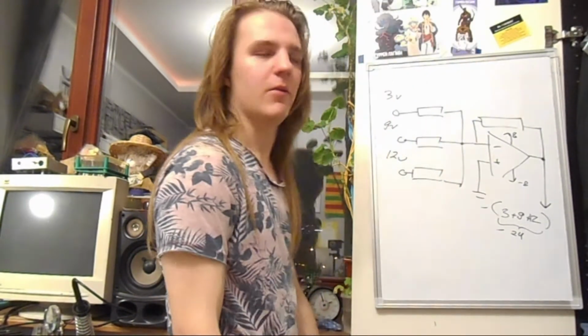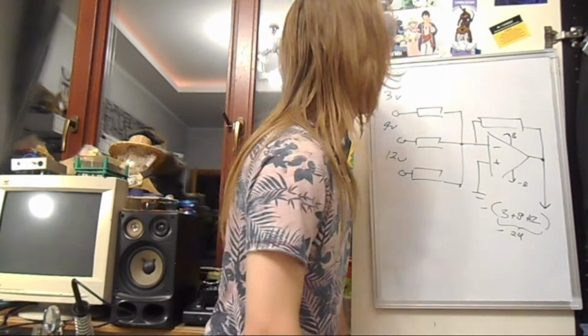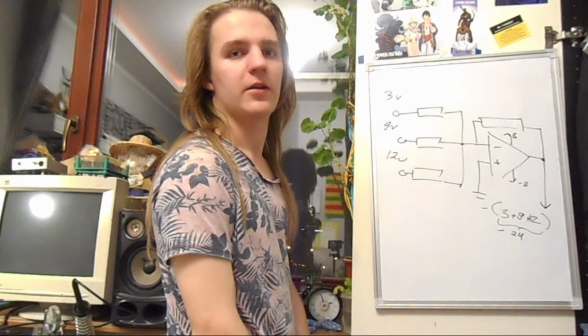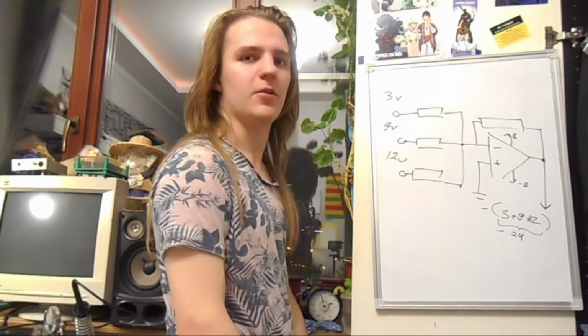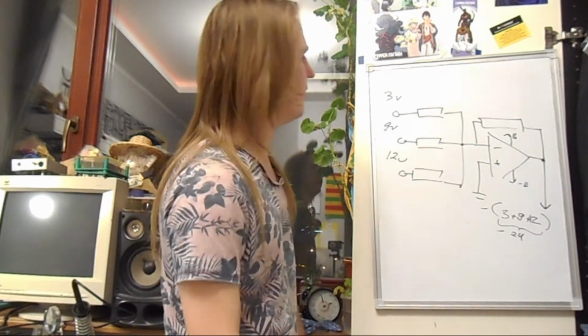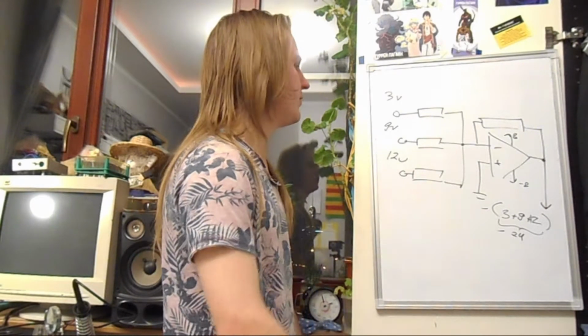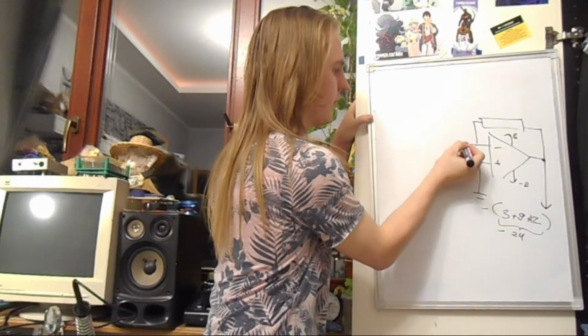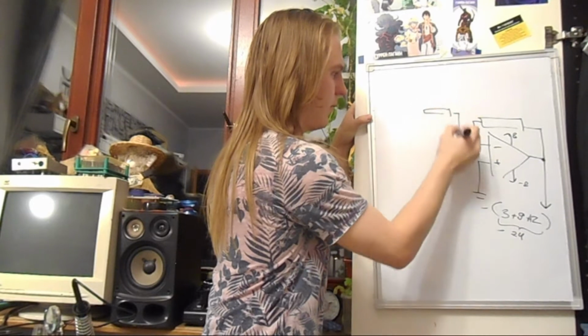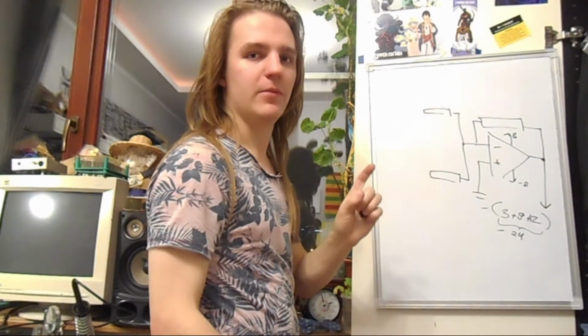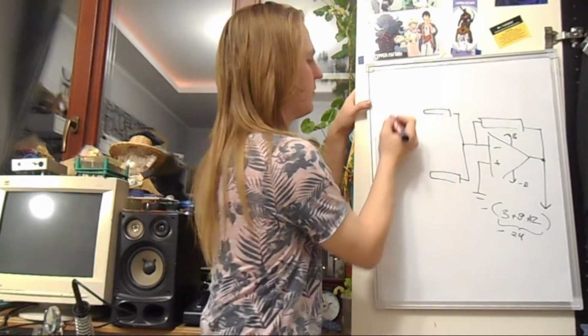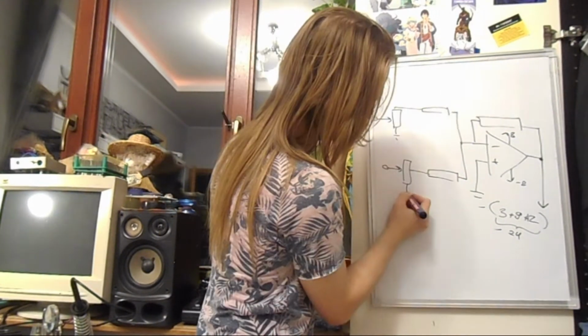How can we evade that? Well, the answer is simple. We just need a volume control at the input of each channel, so we can trim the volume and then get a non-clipping value. Now we will have two channels, one here and one here. But for each of them we will have our signal going through a potentiometer.